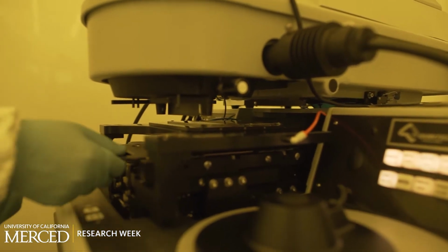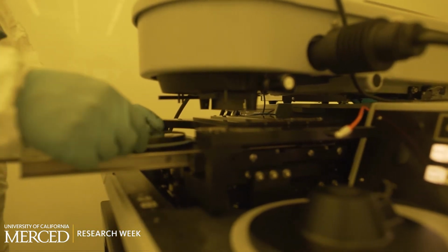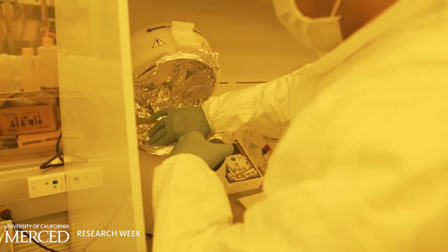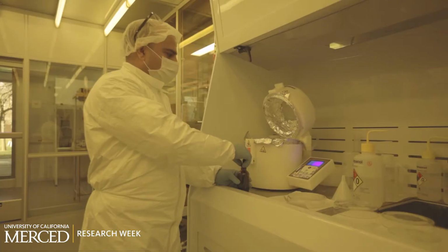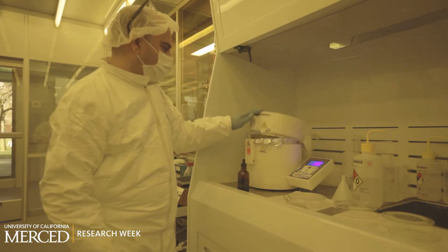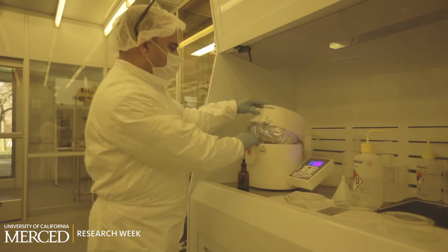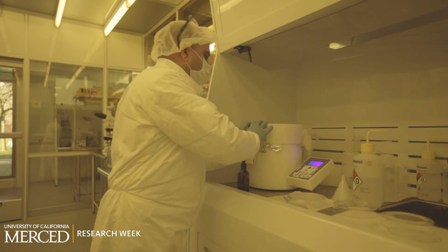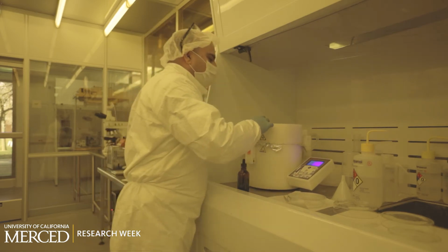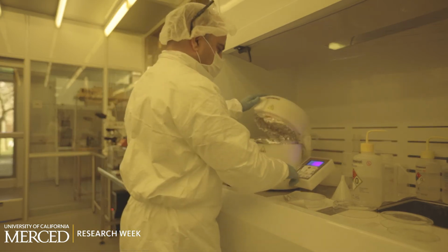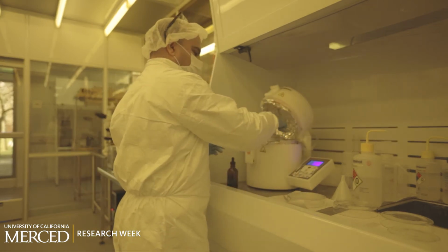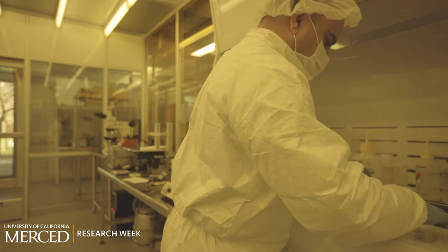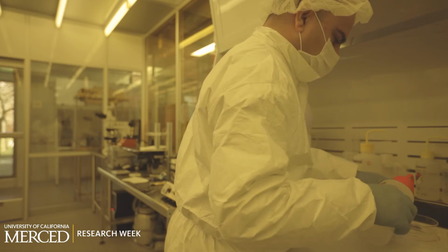Photolithography is the process by which patterns on a material can be defined using light. It is the means by which small-scale features are created. Photolithography utilizes three basic steps to transfer a pattern from a mask to a wafer, and those are number 1 coating, number 2 exposing, and number 3 developing. We coat a photoresist using a spin coater. A photoresist is a photosensitive polymer.